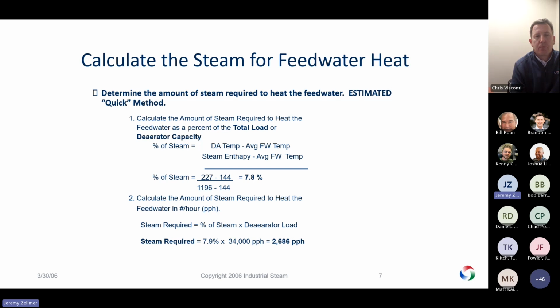I know in a lot of these we're using a deaerator feed water temperature of like 225. If we were to dumb this down and say we were just using a feed water system, you'd be looking at temperatures in the 180 range instead. However, we are using the DA as typically those are more rigorous. It's more important for them based on the fact that we're pumping hot water at the deaerator. So that's why we use this in most of our examples.